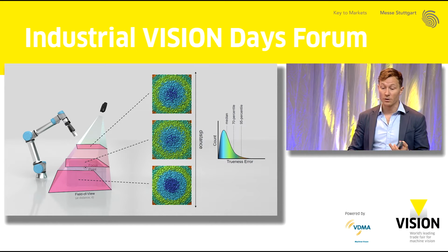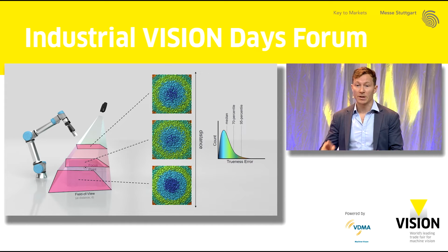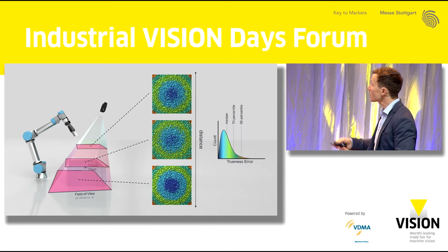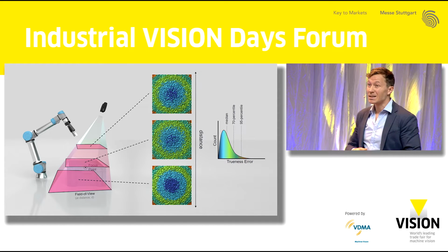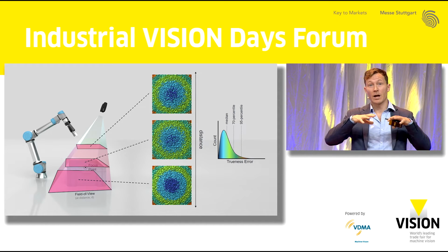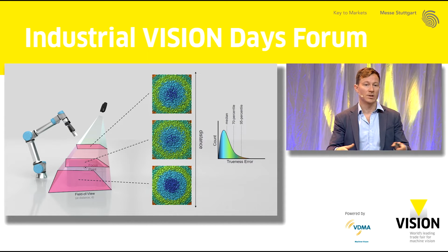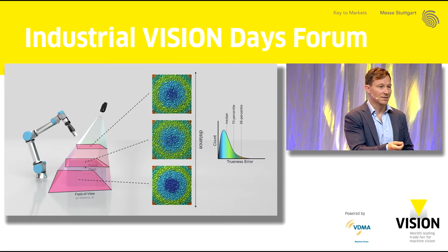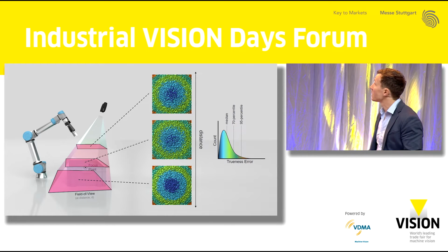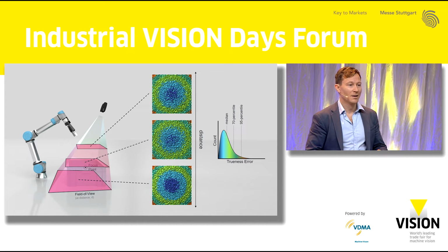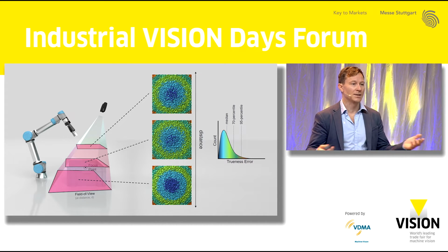You have to have very tight control of the reference object, the temperature, all the systems that are working at this to really get this right. So for every camera that we test this way, there are approximately 20,000 unique XYZ coordinates that are correlated with their real point. And then we gather all this together, and we make some statistical analysis and say, for example, what is the median error, or what is the 70% chance of an error, or limit of an error, etc.